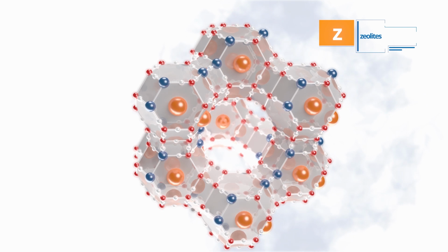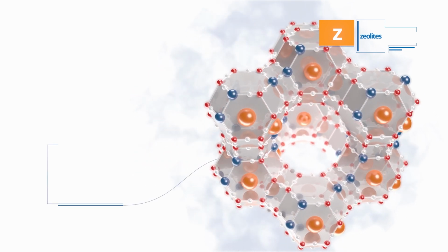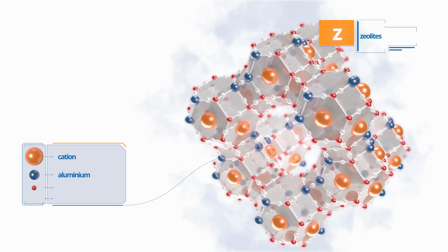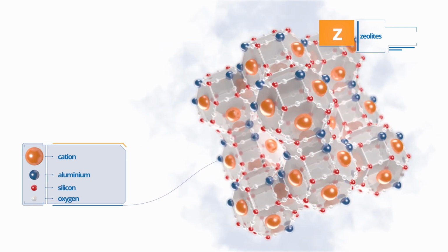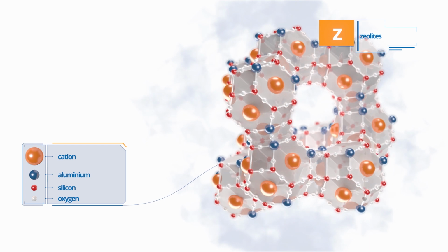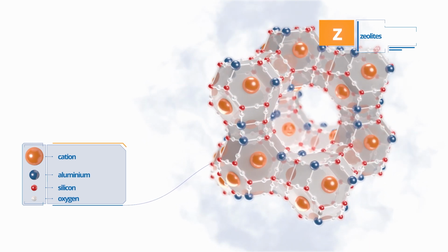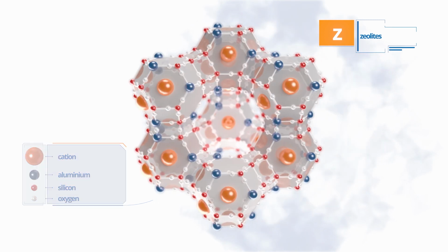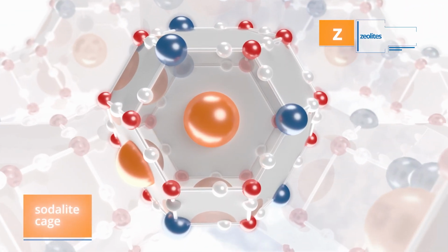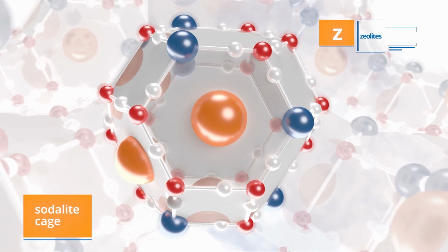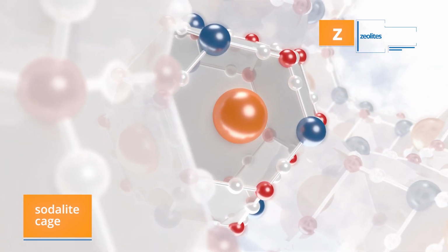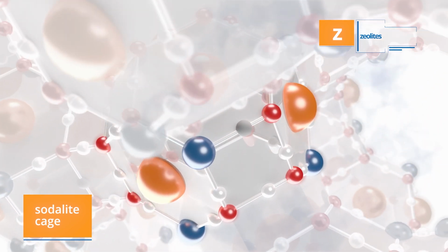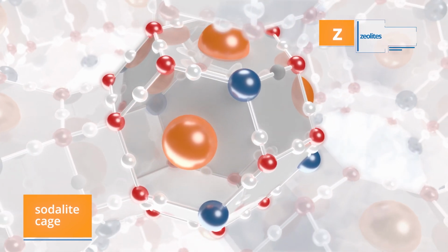The basic crystal structure is tetrahedral, with a silicon or aluminium atom in the center of the tetrahedron and oxygen atoms at the corners. These basic building blocks combine at their oxygen atoms to form a cell structure with well-defined pores and a specific diameter. This elementary cell has 8 supercavities. The unit cell size is the distance between repeating cells in the zeolite structure. The selectivity and yield of the catalytic cracking products will differ depending on the unit cell size.